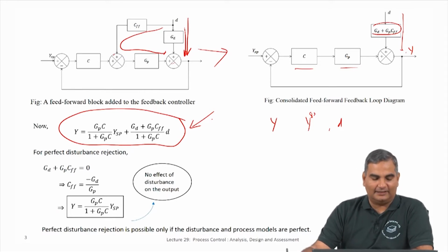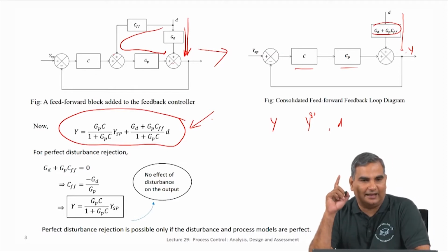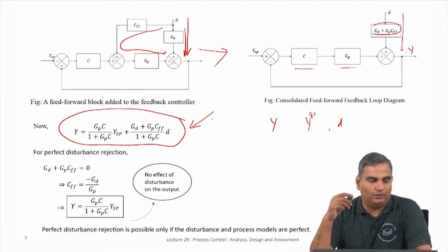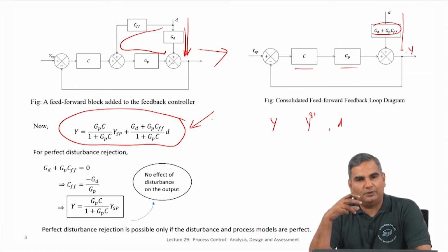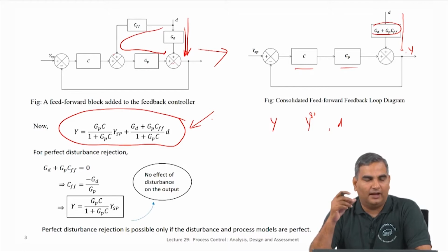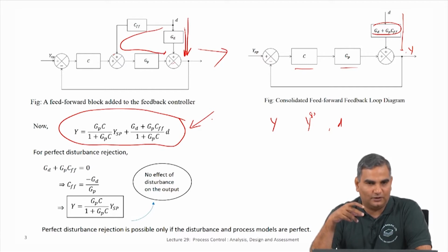something interesting has happened. Remember, in the cascade I said somehow if you had the standard feedback loop, you have to change your hardware in such a way that some part of the transfer function gets changed. So, in that case we had GP2 GP1 as GP, and then we showed that the GP2 could be converted to GP2 C2 divided by 1 plus GP2 C2, right.